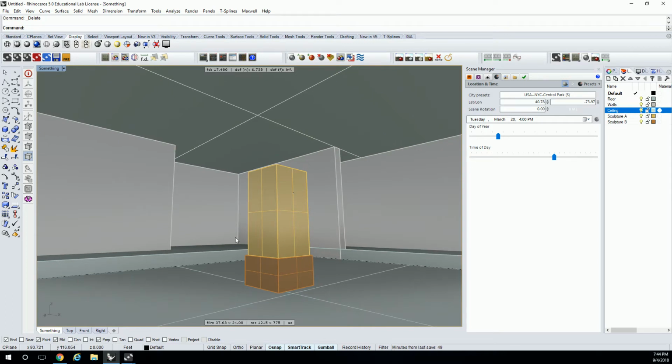Inside the space, we are going to have to add light, and there are two primary ways to do that. You can add light through Rhino light families, basically the lighting tool, or you can add light by creating materials and applying them to objects. We're going to start with the training wheels, which is using the Rhino lights, which are actually pretty darn good. We're just going to stick with direct down lights and spot fill lights, just to begin.